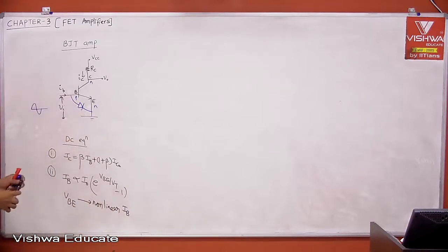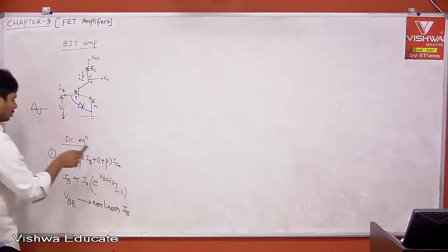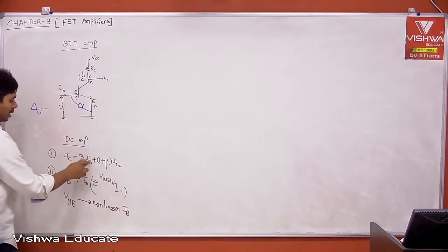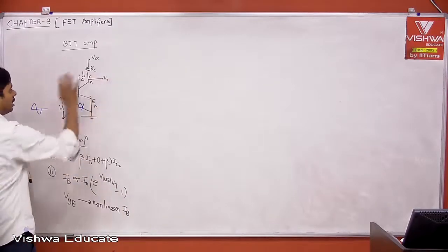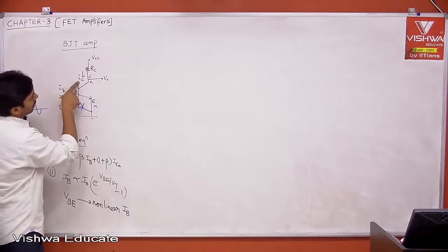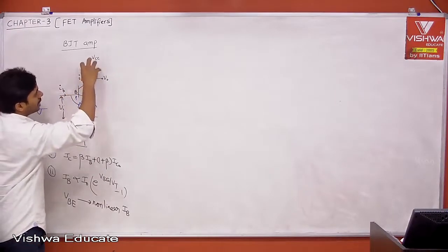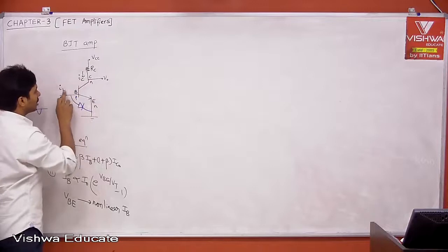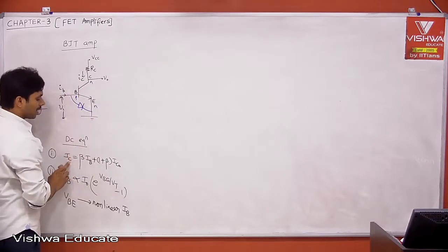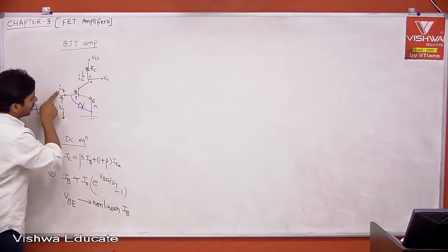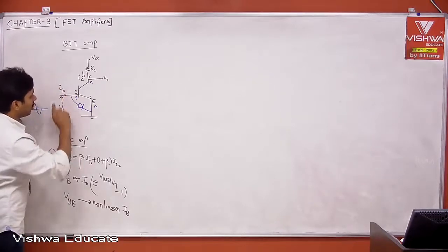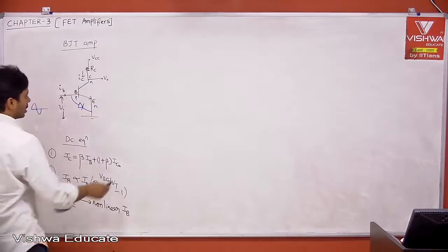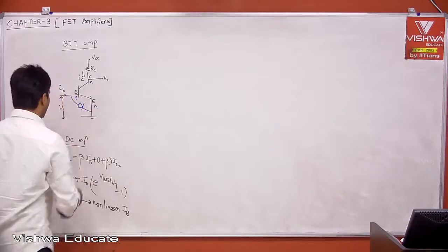When you get non-linear IB, then what is the relation between IB and IC? I can say this is linear. Therefore, IB to IC is linear, and IC to output voltage is also linear. Whatever output current you pass through RC gives a linear relationship. Output current to output voltage is linear, output current to input current is linear. But input voltage to input current, the VI relationship of a PN junction diode, is non-linear. Therefore, the relationship between V0 and Vi is non-linear.